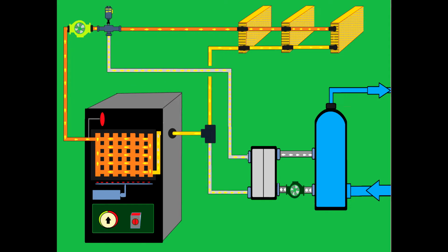If you follow the heating agent line now, you will observe that the heating agent goes hotter into the radiator and comes out cooler. The difference between the flow and the return is exactly the temperature that has been exchanged with the air. That gives us heat.